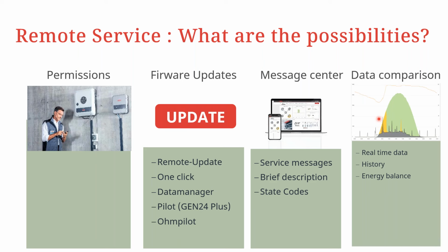So just to recap, looking at the possibilities. It is possible to integrate access permissions in SolarWeb. You can either have access to it as owner, supervisor, or guest. As a guest, you can only have access in the read-only version, meaning that you can only read out information but you cannot perform any change. As a supervisor and owner, there is the possibility of making some changes in the system.